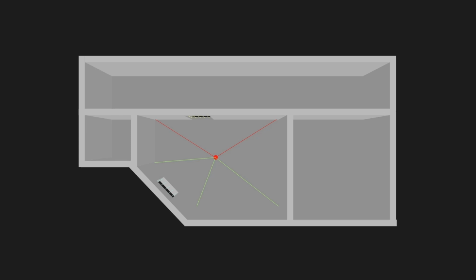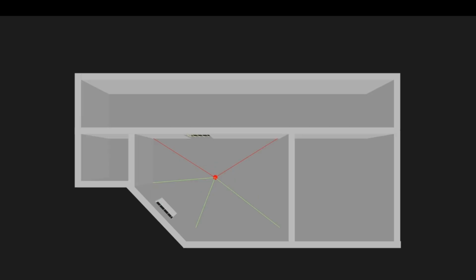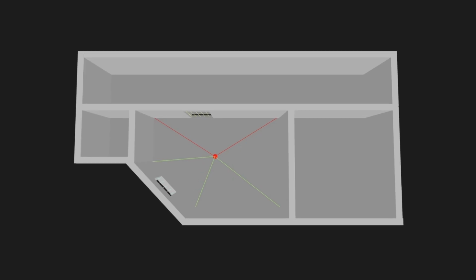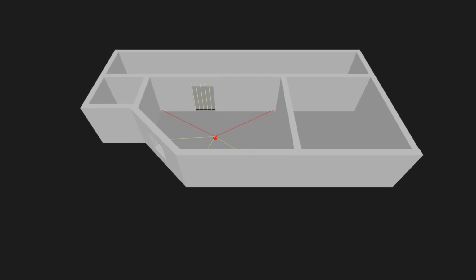And the green ones denote an exterior wall because there's only a single hit when we do ray casting towards the wall. So if we continue the animation a bit, zoom in a bit more from a different angle, in the same step we also did vertical probings from the floor mesh itself, and we also did wall segments so we can see which wall is the longest and on what side of the opening it is.